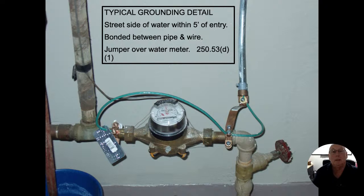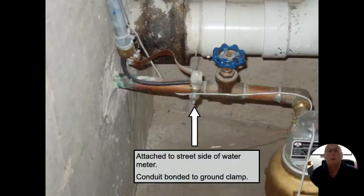That GEC, in this case, is probably about 100 amp service because that looks like a number 6 copper wire. And it needs to go to the street side of the meter and jump over the meter. This one here, same thing. We connect it, we're on the street side, but we don't have a jumper wire coming back. All right.